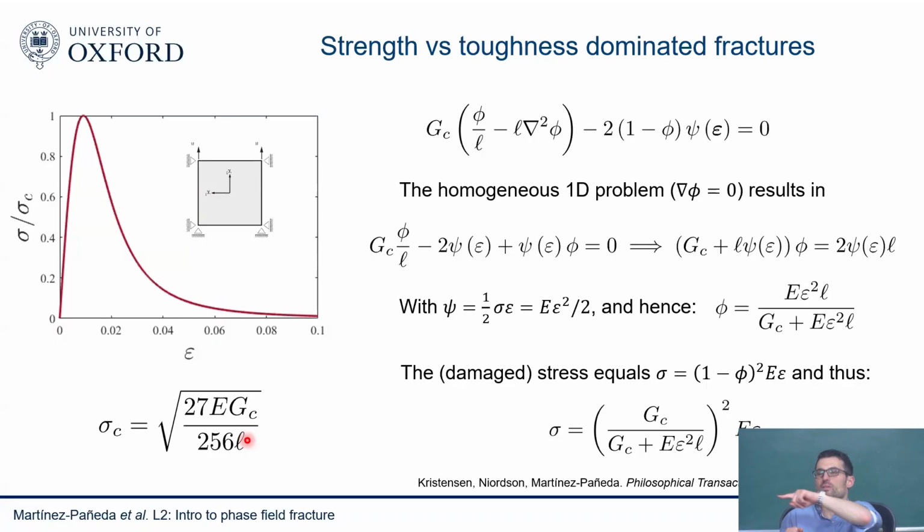If you think of the strength, imagine that you have stresses ahead of your crack. Your stresses are going up. When do you start seeing macro cracking? Normally when your stress reaches some sort of critical strength, then you start seeing this macro cracking. I think I get where you're going. There are other phase field models which are trying to decouple the length scale from the strength. Some of them are quite heavily applied to concrete, so we'll discuss them later on. It's more what we call phase field cohesive model. I have a slide about those things.